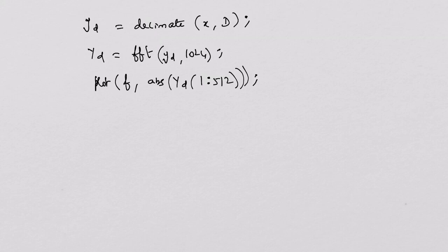You will ask me a question, sir. Instead of using the plot command here, let me have subplot. Yes, it is agreed. Subplot of 3 comma 1 comma 3. Let me have the spectrum in a separate part. Very good. You can view the signal.